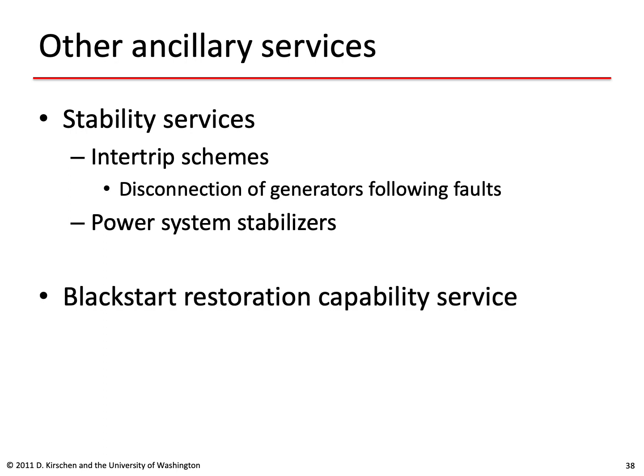Another service that system operators need to have is the ability to restart the power system following a blackout, or black start restoration capabilities. So they will pay generators who are able to start their generating units independently, using either small diesel generators or hydro generators. They will pay them some extra money for being there in case there's a blackout and the system needs to be restarted.